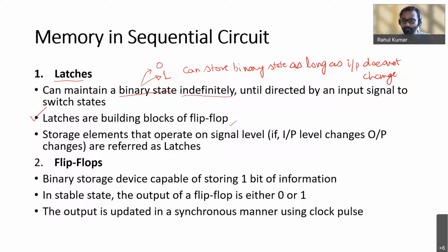Now in the case of flip-flops, again using latches we build flip-flops. They are again binary storage devices which can store 1 bit of information. However, flip-flops operate in a synchronous manner. In the case of a flip-flop, along with your input, you also have to provide a clock pulse.